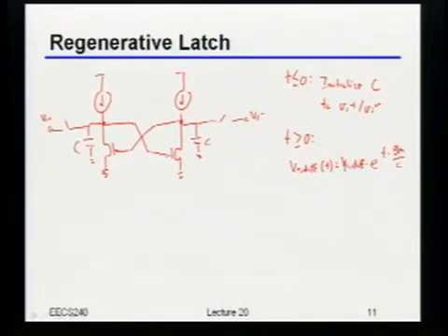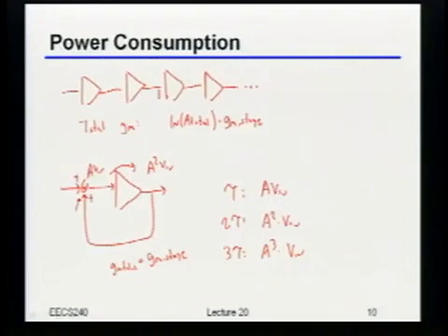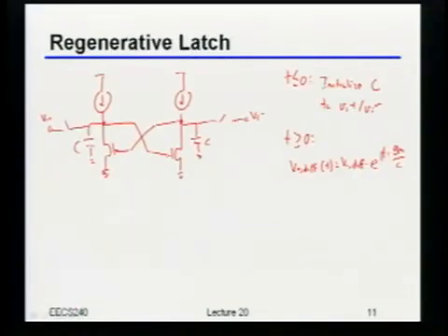So why do I mention this? Because obviously, the smaller the initial differential signal you put in, the more time you need to rail that all the way back to a fixed value, right? Which makes perfect sense, because if we needed a smaller input signal, that means we need more gain to get to a certain swing at the output. That would have meant we needed more stages. Here, more stages just means more time, because I need that time to circulate through the loop.